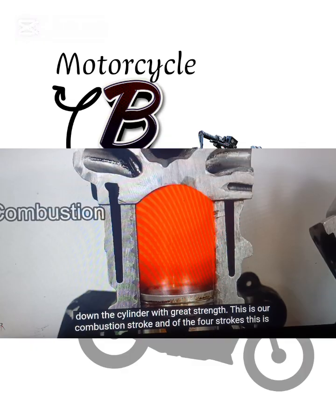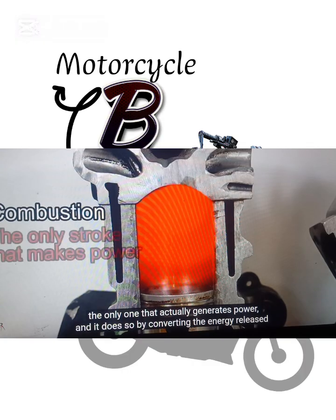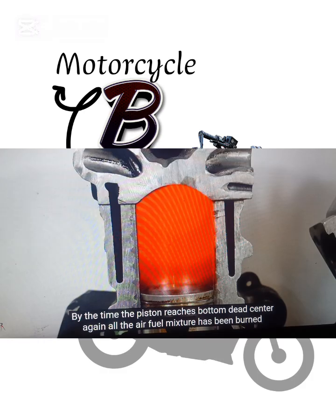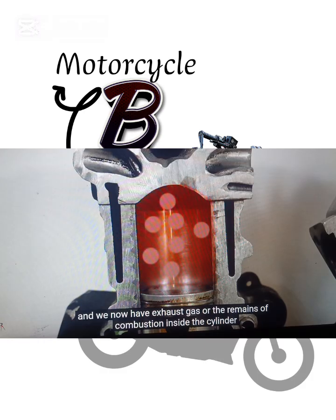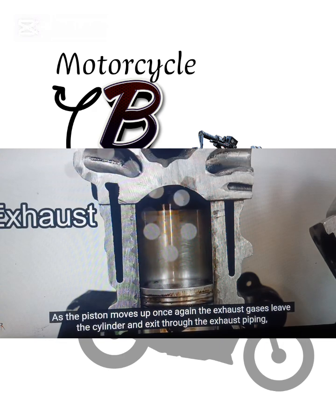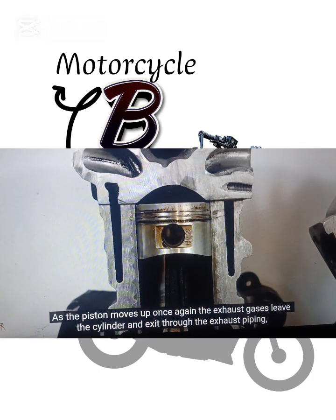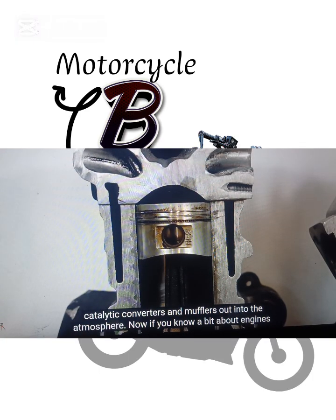This is our combustion stroke, and of the four strokes, this is the only one that actually generates power, and it does so by converting the energy released by combustion into motion of the piston, which then turns the crankshaft and ultimately the wheels. By the time the piston reaches bottom dead center again, all the air-fuel mixture has been burned, and we now have exhaust gas, or the remains of combustion, inside the cylinder. As the piston moves up once again, the exhaust gases leave the cylinder and exit through the exhaust piping, catalytic converters, and mufflers out into the atmosphere.